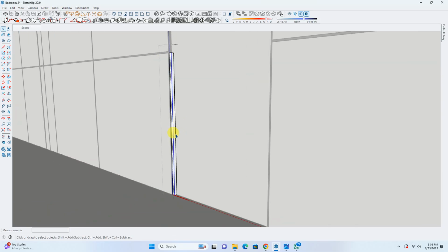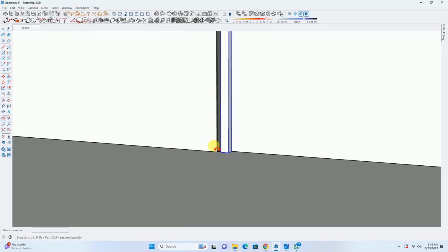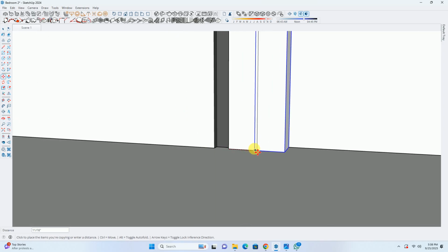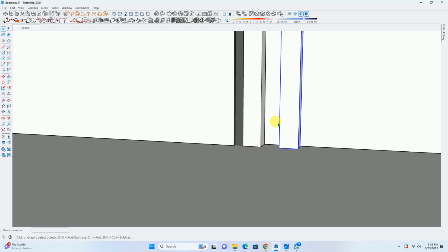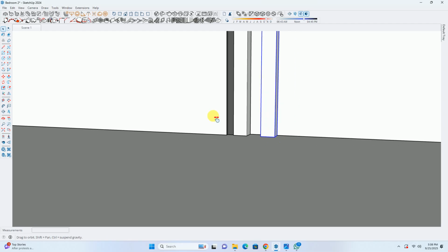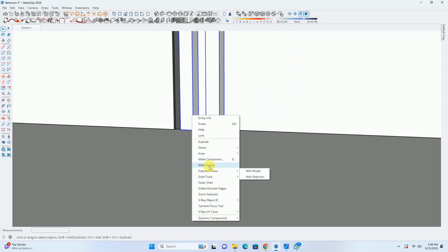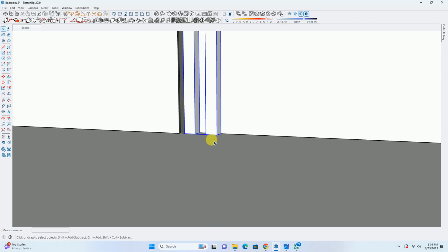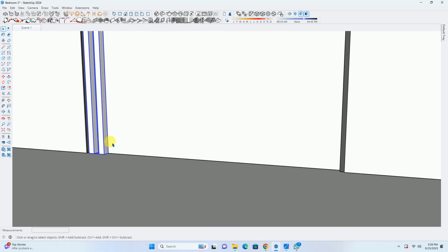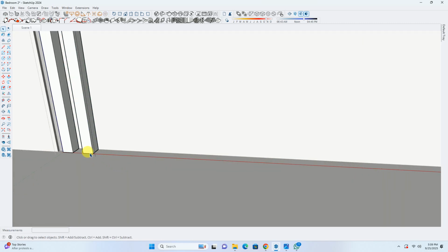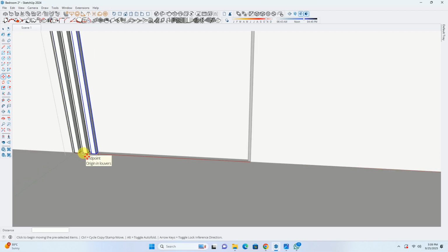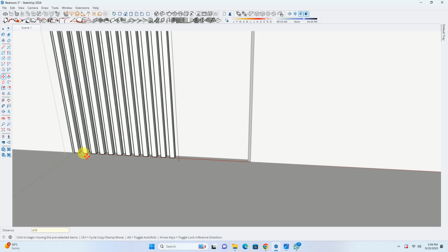Okay. And now after creating one louver, I'll copy this at a gap of 1.5 inches so that we can have a gap of 0.75 inches. Now I'll select these two elements. I'll convert them into a group so that we can keep the louvers in a single group element. Now I'll double click on this group so that we can go to the group editor. Now we'll select it from this point and drop at this point. Now I'll press X and type in the value as 10, so we can get the multiple repetition.